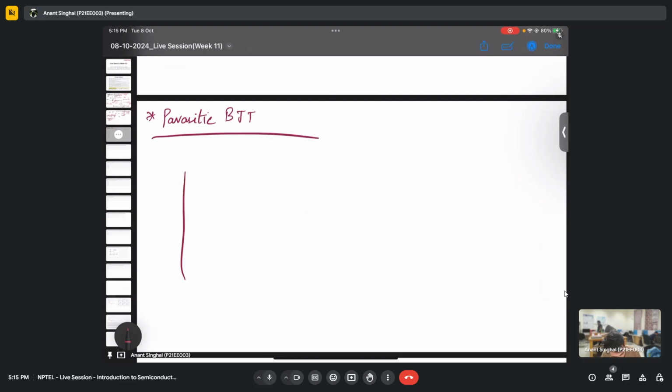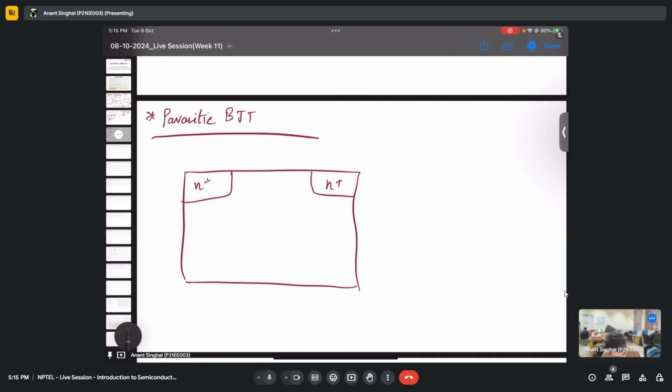So we have already studied a lot about MOSFETs. We have this drain VD, we have this oxide, and we have this gate. In general, this is at ground. This is what we are increasing to greater than VTH, and the main thing is that we keep on increasing the VD. So what happens in a MOSFET? Let's say I am increasing this VD.